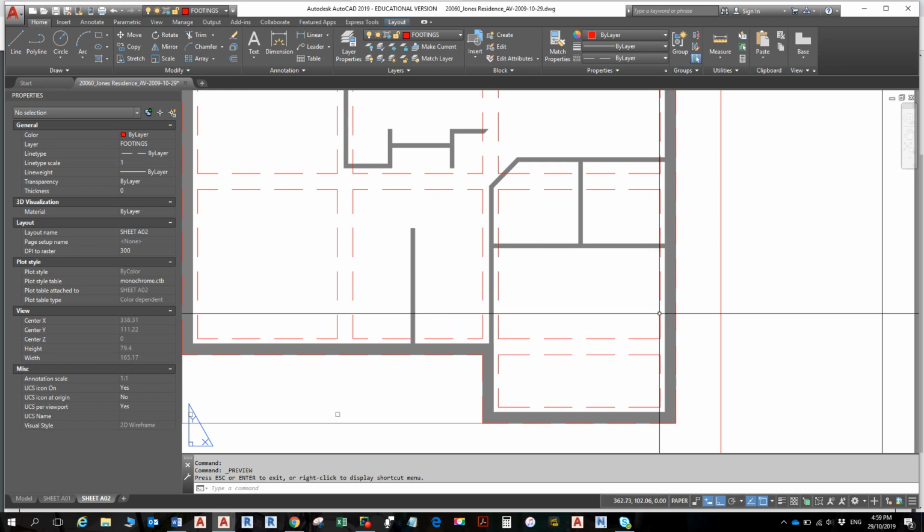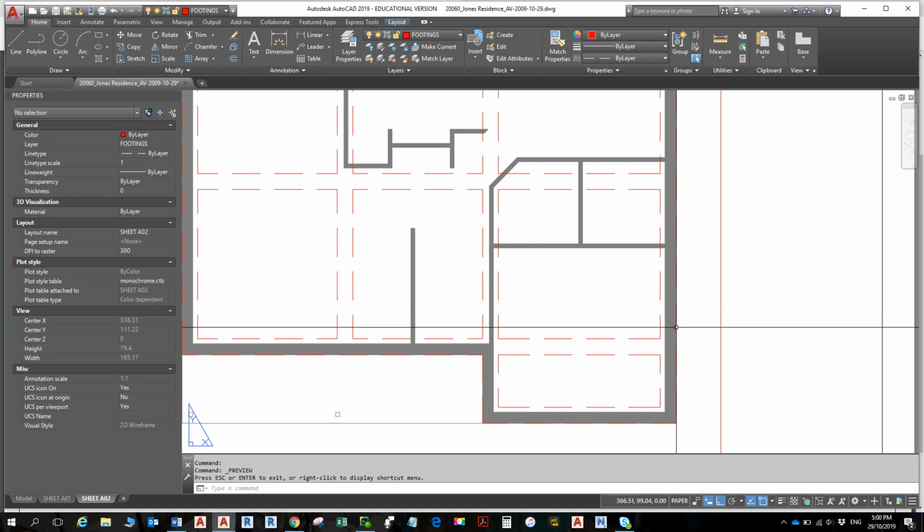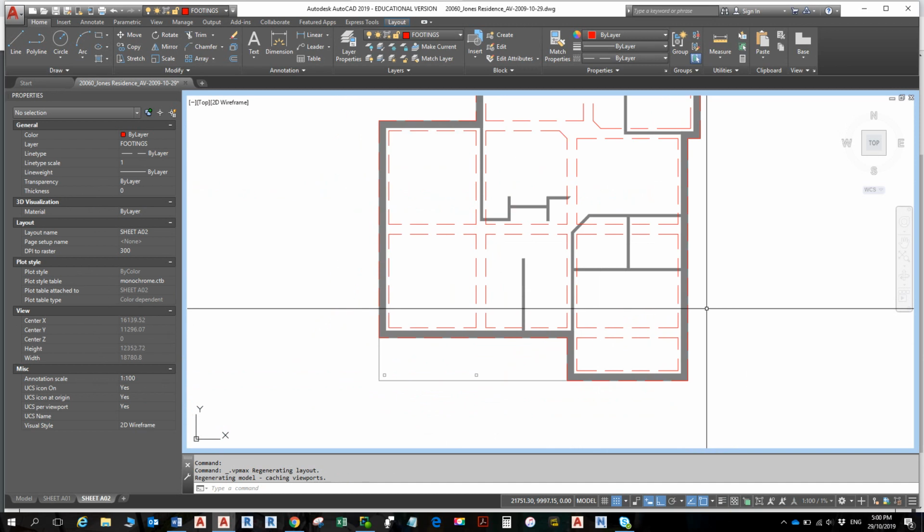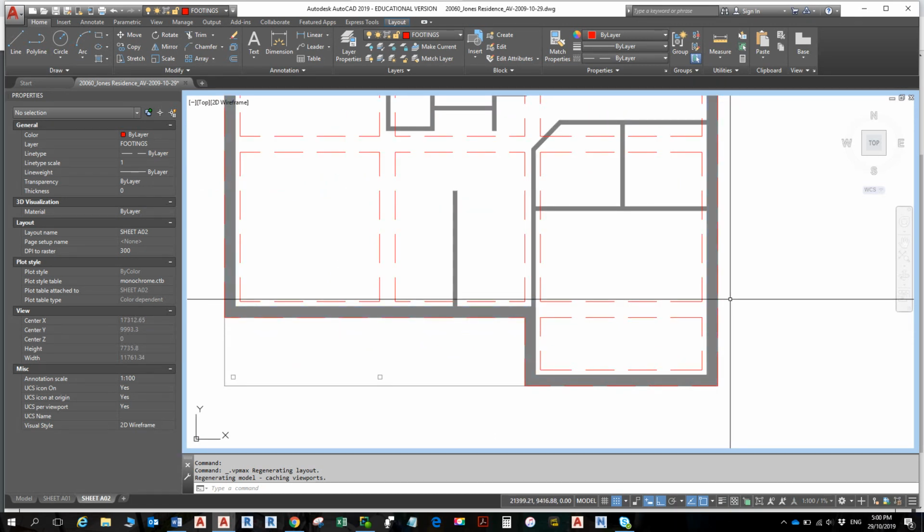I don't know if you've done anything in construction, how timber frame brick veneer works. So there's about a 30 millimeter rebate, a lowering of the footing there. So easy to do that. And then we're going to get onto the post for sure, yes. They're 600 by 600, the pads. So let's go with this.